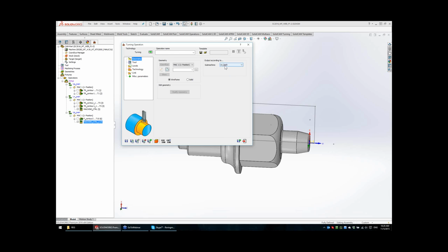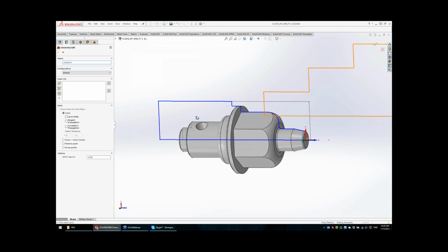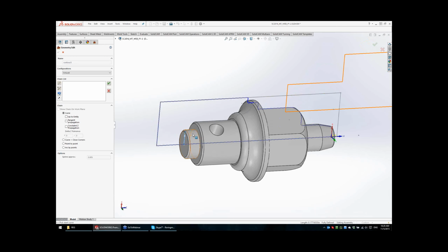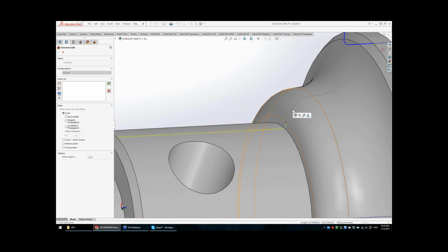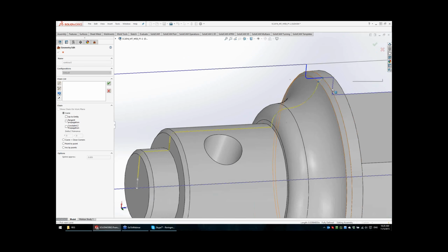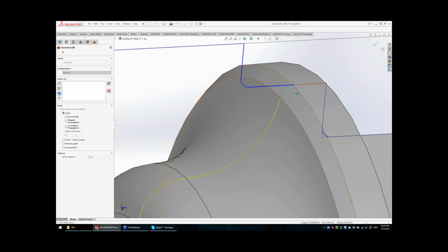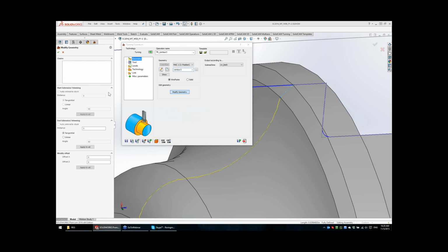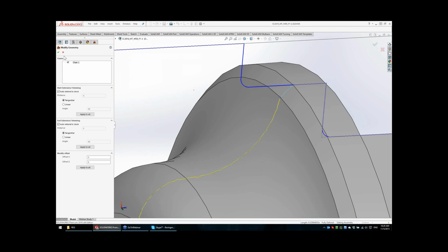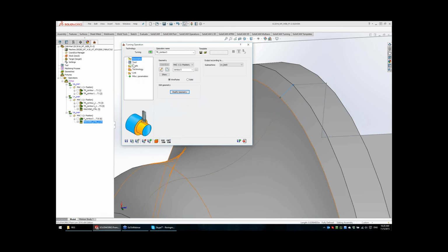Lower back. I will work with lower turret on back spindle and select the geometry from here and up to here is enough because I already see the rest material. Modify geometry, extension, no need to do extensions.